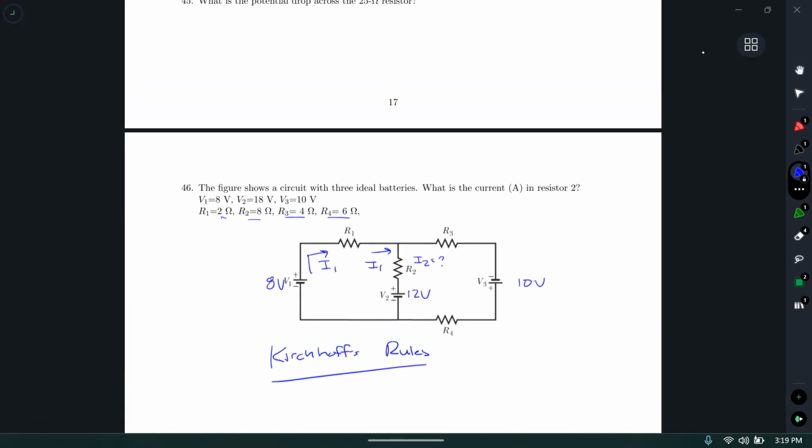Okay, then I look at my 2 branches. Because this is a junction, I'm saying of 3 branches meeting. And I would say, okay, I should have a current going through this lower branch and going through the right branch. The directions I draw them also doesn't really matter. I can be wrong about this. So I'll call that I2 and I3.